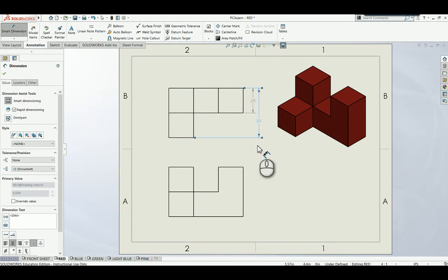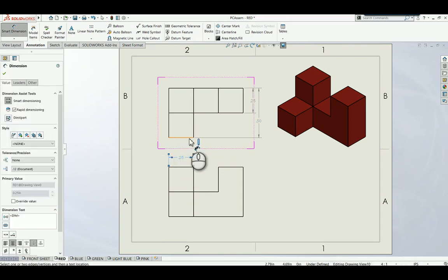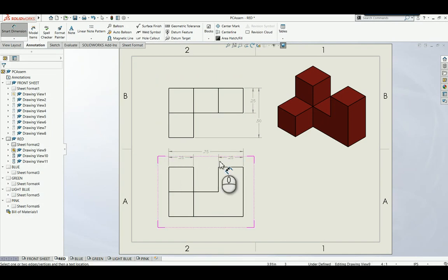On my front view, I'm going to give the width of this jut out, which is also the width of this jut out on the top, the block that extends from the front. And then the other side, simply because I like symmetry. And then I'm going to select that edge and this edge and drag it up. The other benefit of putting the 0.25 here and here is that my 0.75 is more clear due to the fact that it's centered and there's nothing below it.